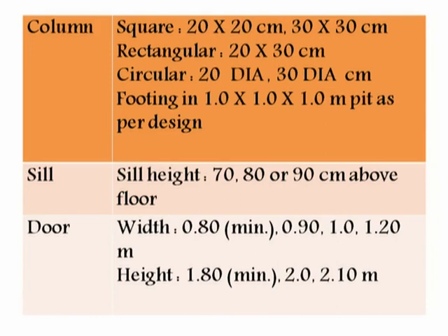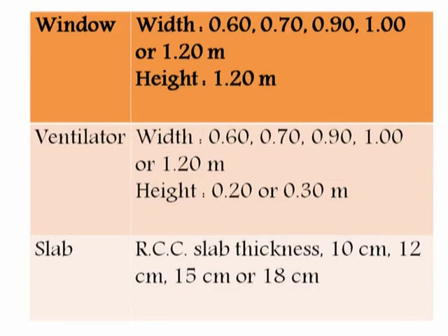The height of the door is kept at 1.8 meter as the minimum height, and 2 meter and 2.1 meter height is also provided for the door depending on the size of the room. Height of the door is 1.8 meter, 2 meter and 2.1 meter.